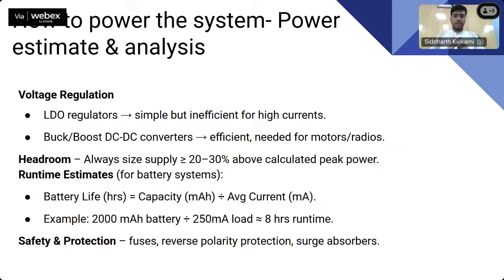Now there are scenarios where there might be three different power levels. You might have a motor that runs on 12 volt. You might have a microcontroller that runs on 3.3 volts. And you then might have a servo motor that runs on 5 volts. So what do you do in that scenario? Use something called low dropout regulators. So there will be two things.